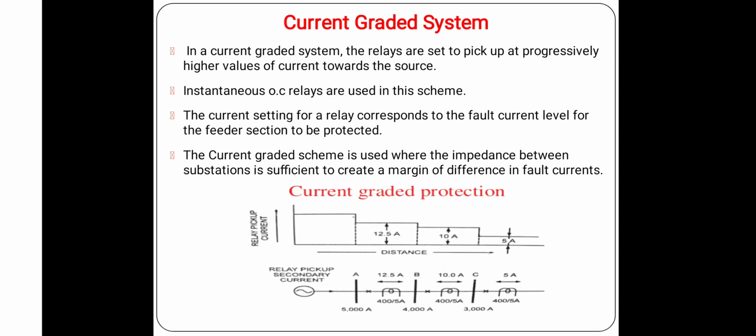It is basically based on the fact that the short circuit current along the length of a protected circuit decreases with the increase in distance between the supply end and the fault point or faulty section. We also say that term.